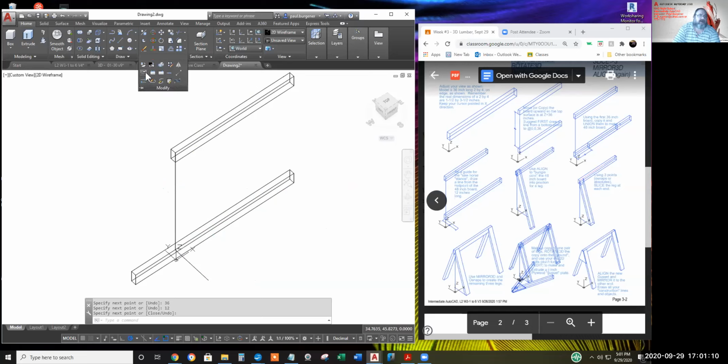Again, drop down, click a line, select the 48, enter. Bungee cord from there to there, bungee cord from there to the midpoint of the proper edge. And now which corner do I select to bungee cord to this chalk line? You know, either one will work, but the feet of the Sawhorse will be slightly different by the width of the 2x4.